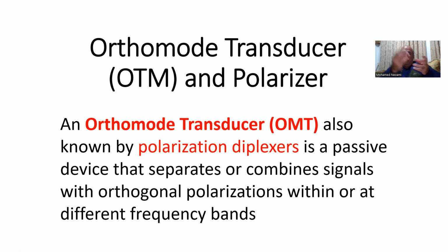So it can receive a signal, like in SATCOM signals, where you have two independent data modulations at the same frequency, one on the vertical, one on the horizontal. What the orthomode transducer does is it gets that signal from the antenna feed and separates them, it diplexes them, or it multiplexes them separately so that you can do processing and receive that signal.